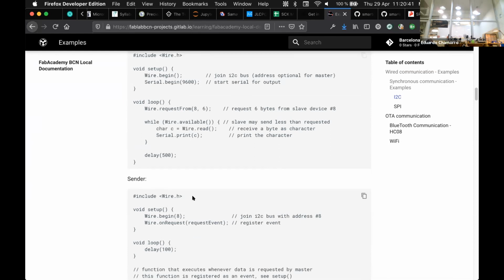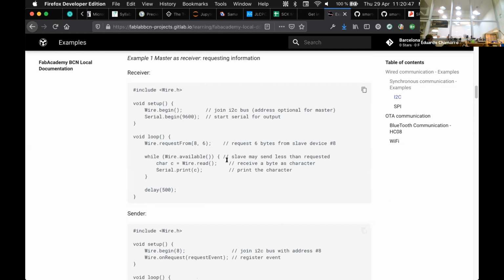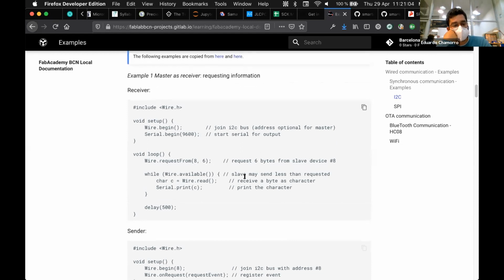I saw in I2C that you cannot see what exactly? It's like two wires, and I don't know how the data is. So you can have two I2C buses. Yeah, you can have that, and you can define that by software as well, or if the hardware has two I2C buses, you can do it. Is it one set of I2C wires with the data separated? No, it's two separate buses. So you would define two wire interfaces.